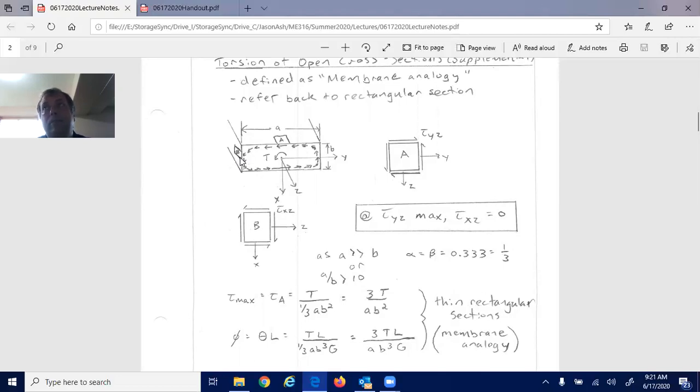And so you essentially get to avoid the combined loading concept. The stress at the point of maximum is the only state of stress present. And so you can look at those two locations separately. The other thing is this is your maximum at A, and so that's the point that you often look at. You're always concerned about what the maximum state of stress is.